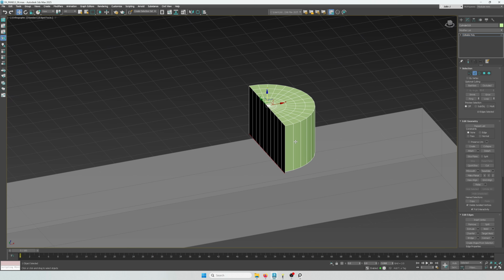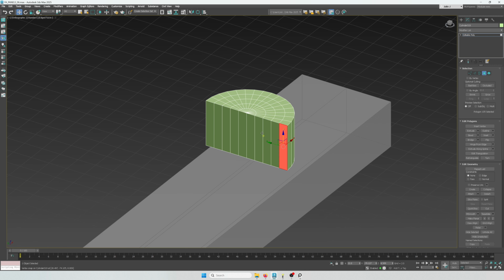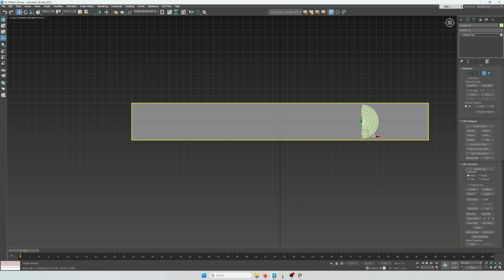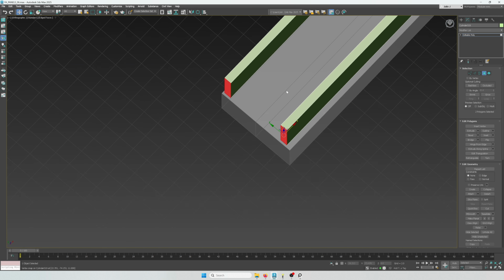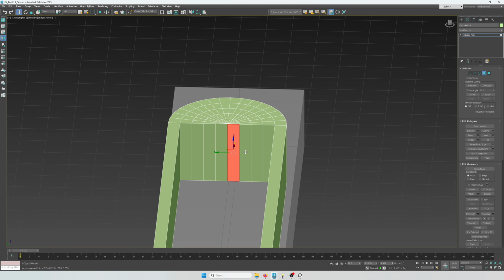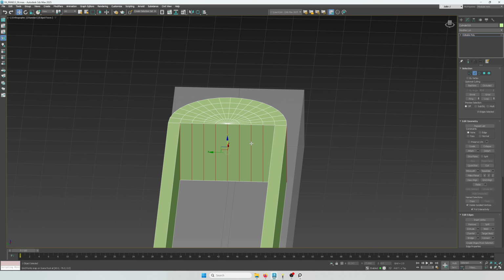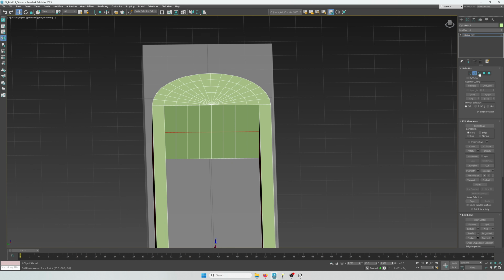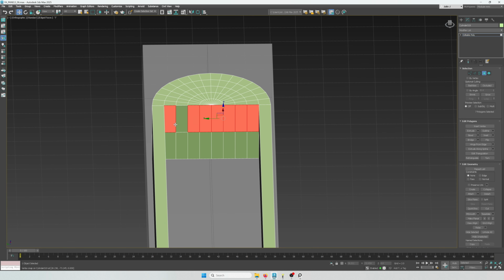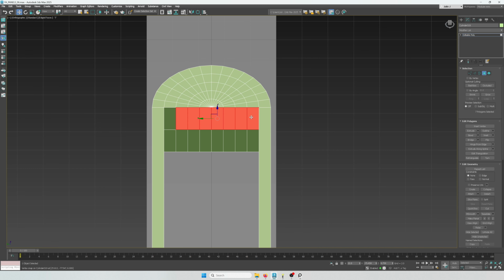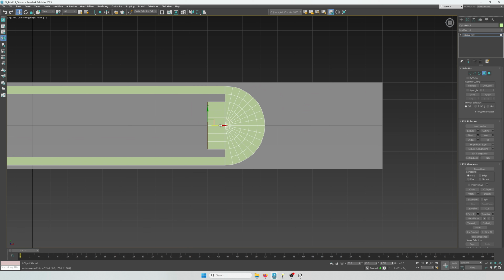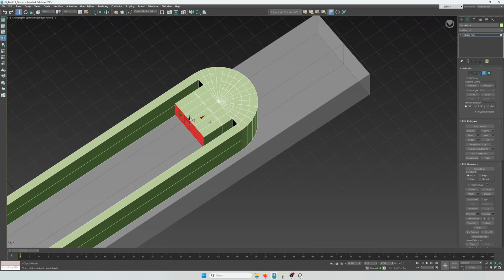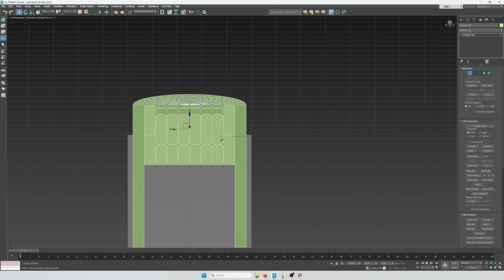Let's delete the bottom half and extrude the edge. This way we don't worry about the bottom and how it's subdividing. Let's extrude these 2 polygons all the way to the edge. Let's add a cut that goes all the way through the middle, and this way we can extrude additional detail. With these faces selected, I'm dragging them to the left to extrude them. But I'm stopping along the way to create supporting detail. As you see, we actually have multiple extrusions.